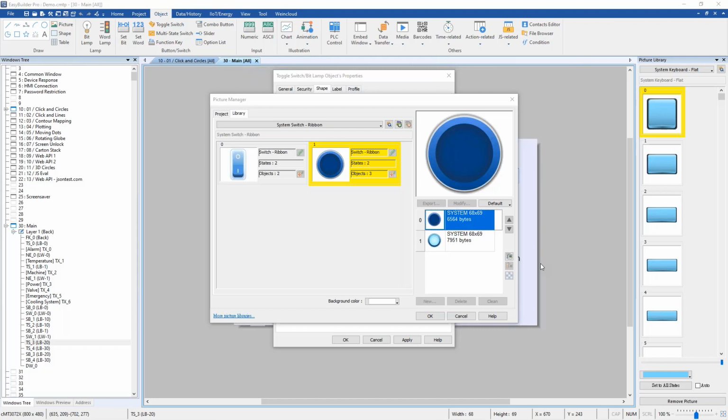All right, so another question is asking what is the difference between resistive and capacitive screen here? Which one is better? Okay, right. So it depends on your scenario, right? Because with a capacitive screen, like I said, the picture on this HMI will just look better, and it has higher accuracy, and it is smoother and the response is faster.